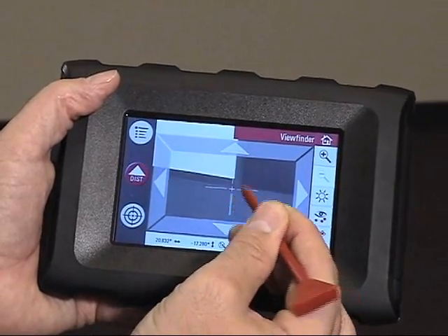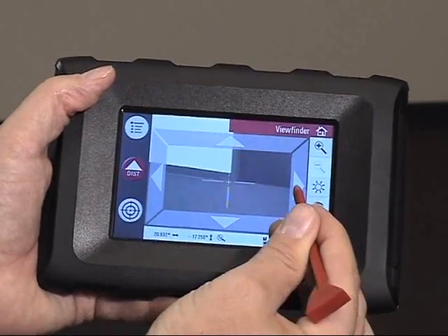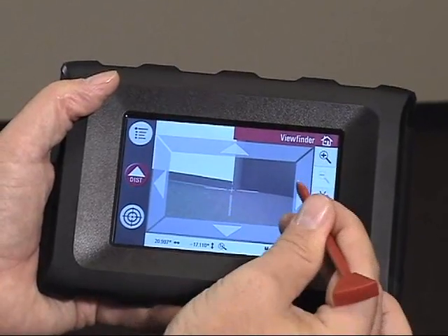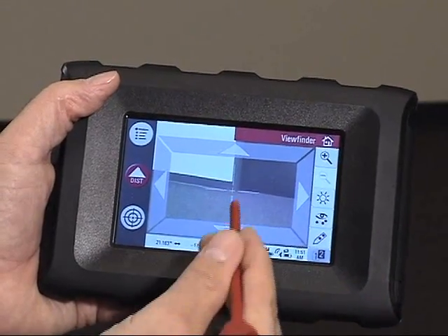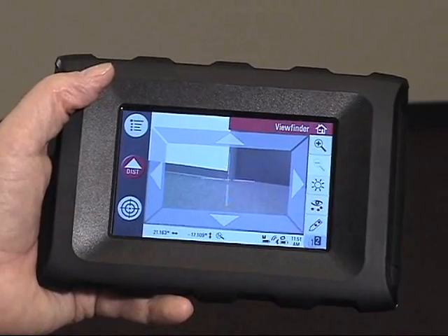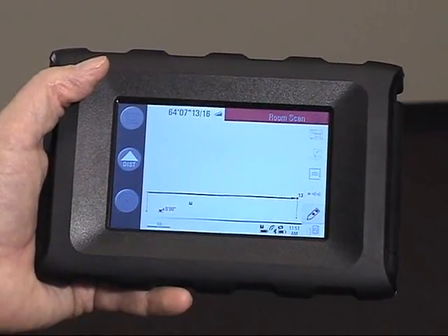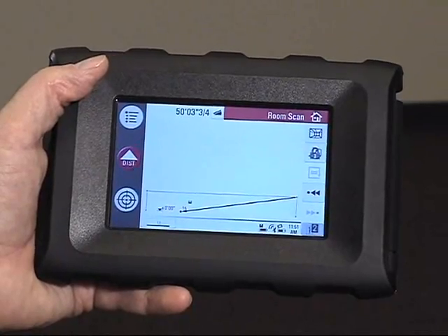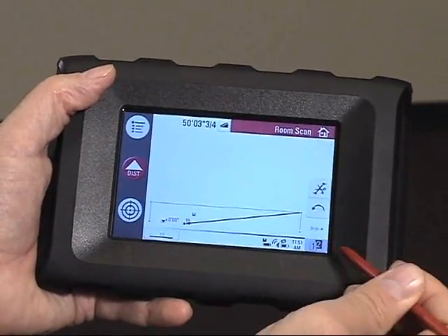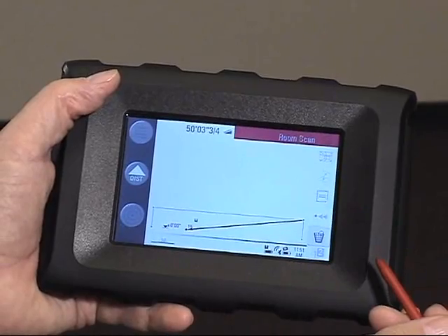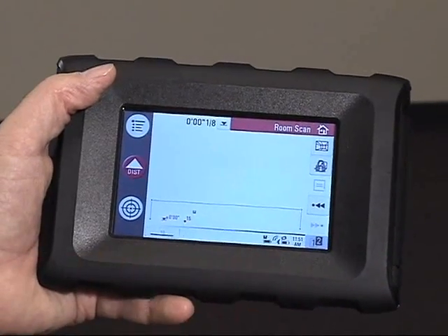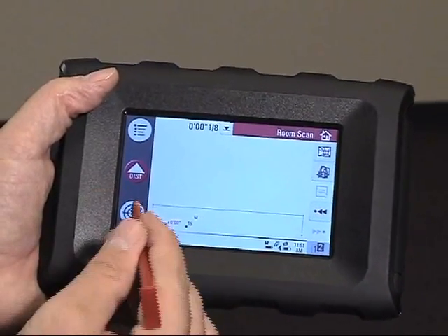I can see my red dot just a little low. I can see the red dot on the door, see the crosshairs in the view screen. To locate, take our first shot. Now, if you remember, the unit's going to want to draw a line from that last point to the new point. So we do need to go to screen 2, cut that point out. So now point 15 is a point all by itself.